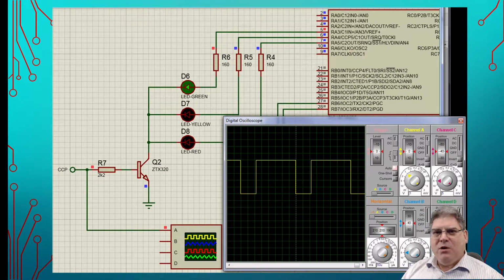Okay. So let's talk about what's actually happening here. And I realize that with the simulation, it's not really showing up very well. And I will link in some other information on PWM for those interested. But basically what we're looking at by pulse width modulation, we're talking about how long the processor's actually pulling that pin high versus the entire clock. And so you can imagine if it's on 100% of the time, it's on, it's maximum. But if it was only on for half the time, the intensity would be half of total, and you could take it all the way down to completely off.